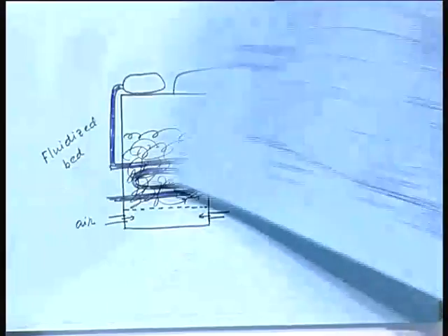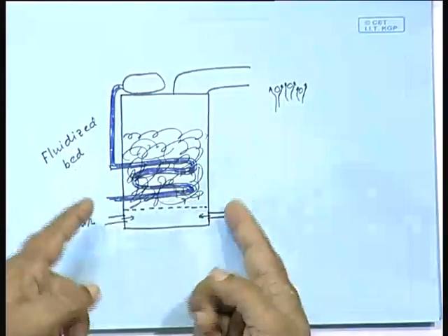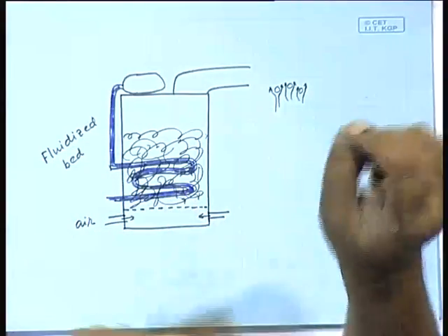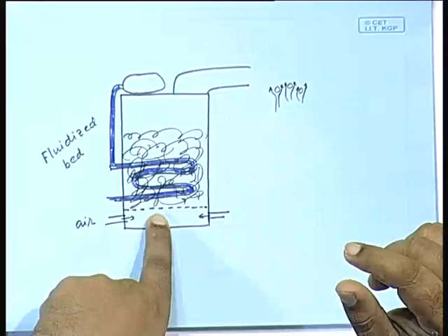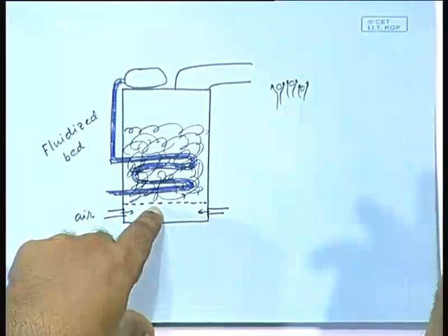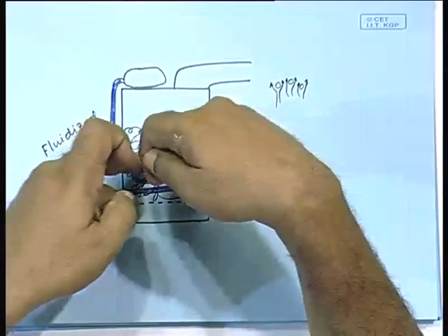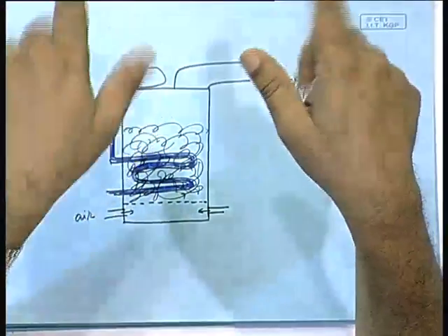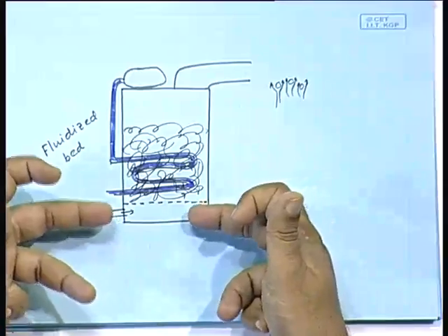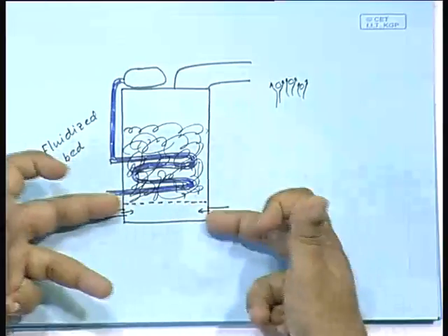Okay. So, and if you mix a bit of steam with that air, what happens? You get water gas. Okay. So the producer gas production system is exothermic. Water gas production system is endothermic. So if you have the proper ratio of air and steam as the input, then what happens?